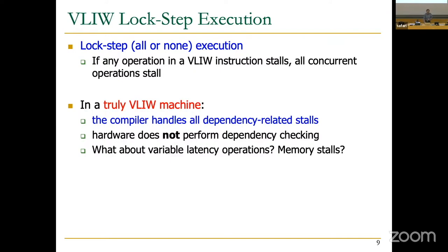What about variable latency operation, memory stalls? This is really the downside. Whereas in an out-of-order machine, this is very simple. I mean, simple in the sense that it doesn't affect performance as much, right? You don't have a dilemma, basically.